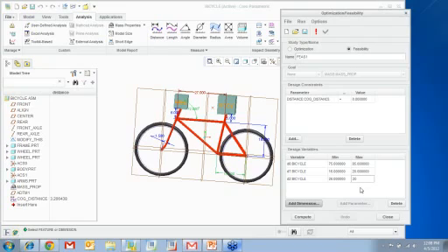Notice these ranges were obtained by running sensitivity studies, because in here we saw the answer was close to 79. If I ran this analysis with say a range from 60 to 75, I'd never get an answer. So by running a sensitivity study, I know if I should use the design variable and also what the range of it should be.